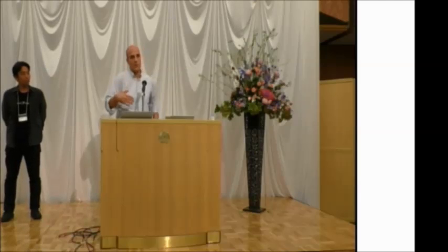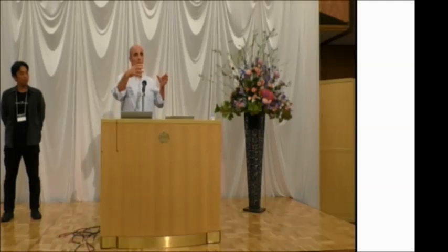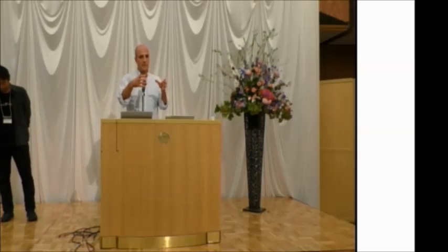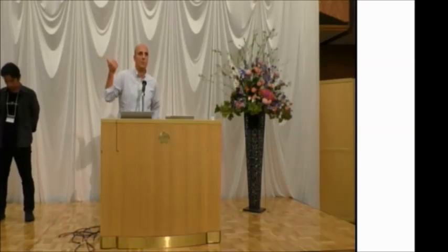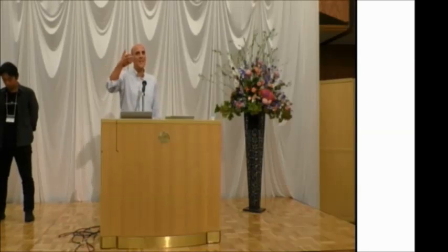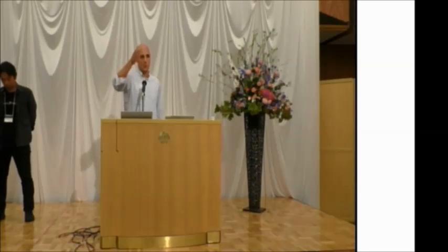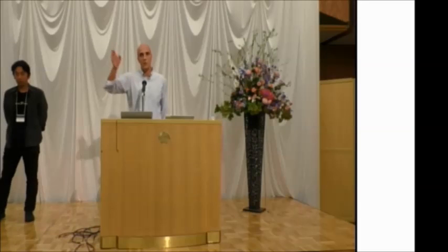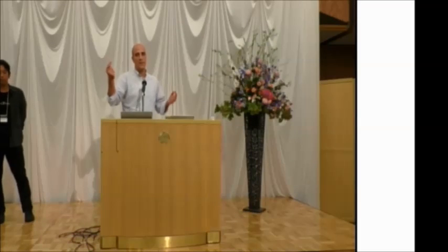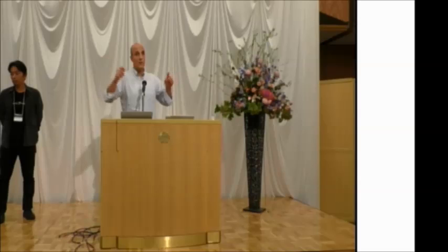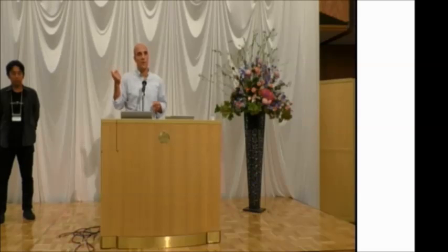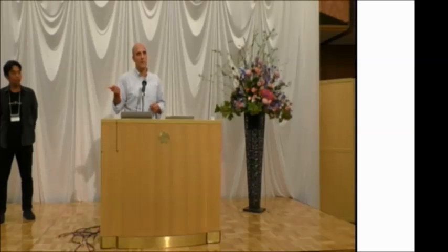The knowledge of the basic features, the basic processes contained in the model, which can be studied with the approaches that I showed you, can tell the numerical people something. For example, where you have to put the boundary condition. Once you know where the waves travel, you know if you have to put a boundary condition in the upstream part or in the downstream part.